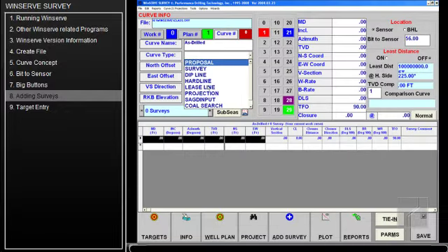But basically, in short, what you do is you create a survey at 90 degrees, and you turn in a very, very short distance, and you establish the direction. For example, if I wanted to go from 0 degrees direction to 90 degrees direction, and I wanted to go 100 feet and then 100 feet in the 90 degree direction, I'd have 100 feet at an inclination of 90 and a direction of, say, due north for 100 feet.